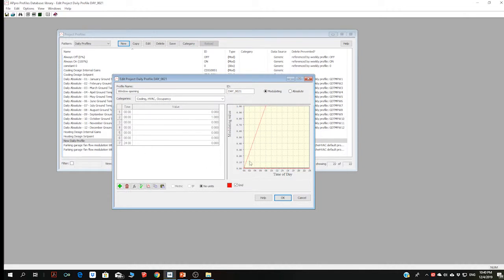So you can see now it turns into kind of a sloping graph, but I'm not gonna have that because we don't open the window at 0 hours. Slowly gonna open the window until it's maximized by 8, because normally people don't do that. So just choose absolute, and you need to copy this because at 0 hours is 0, no opening at all.